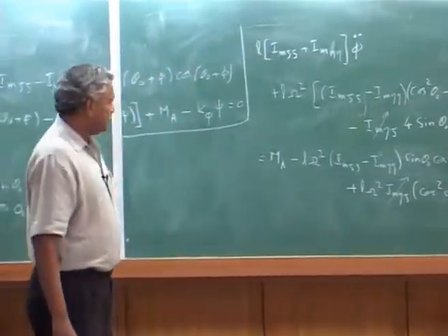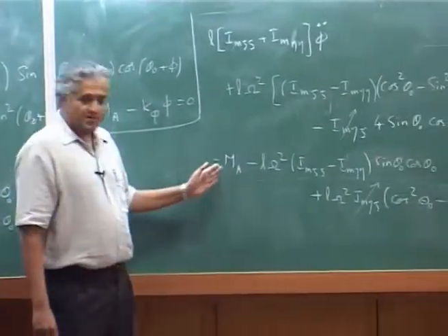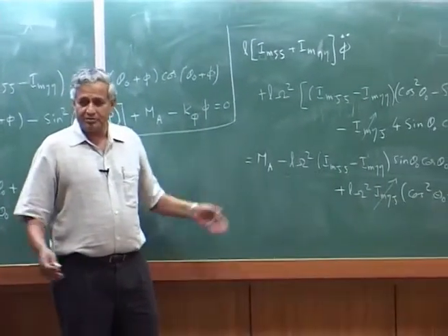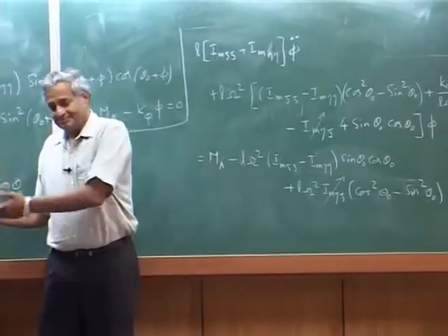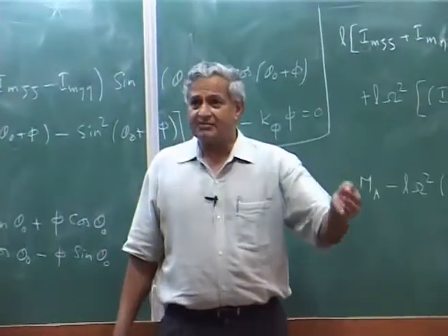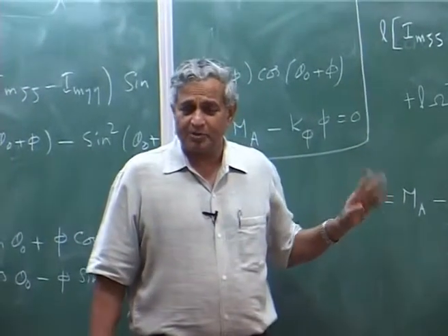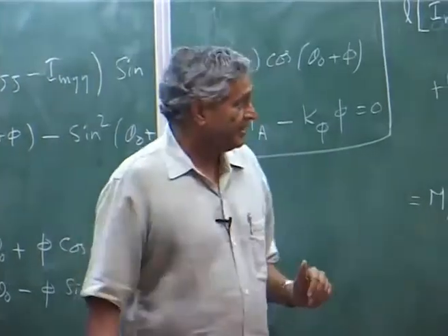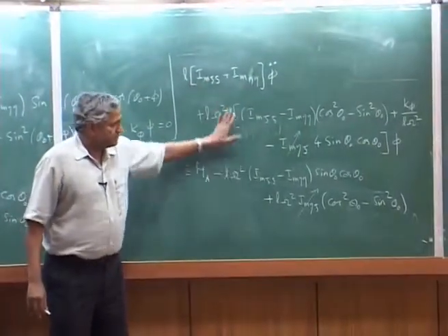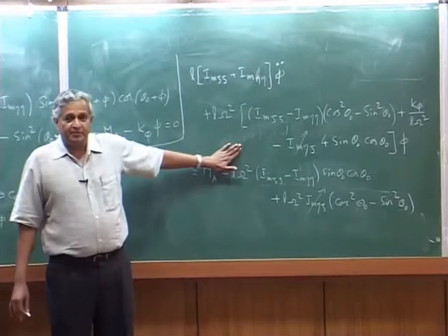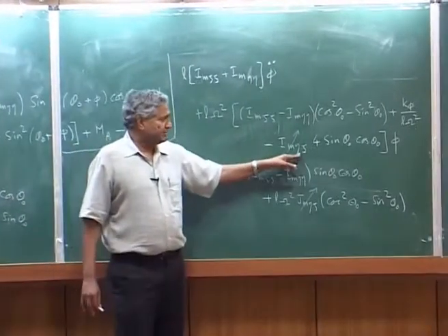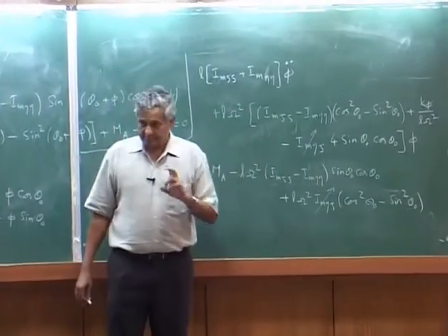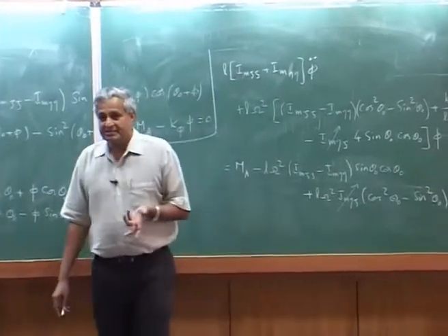Okay. And now I will not write any expression for MA, because this is basically the aerodynamic load. You can use quasi-steady aerodynamic load or a very simple instantaneous angle of attack, take it, put it. They are quasi-static. These are all terminologies in aeroelastic analysis. Okay. This is purely simple torsional dynamics. From here you can say, if my Im eta zeta is 0, what is my frequency? Natural frequency of the blade in torsion.